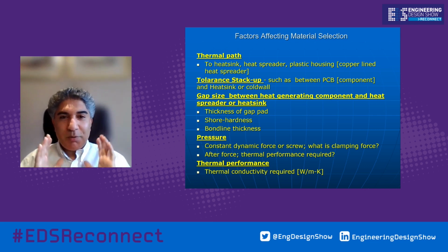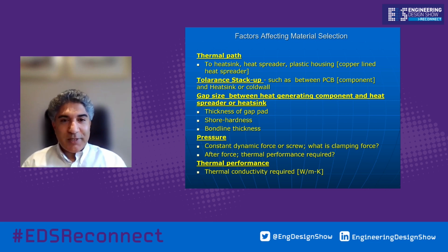Tolerance stack, I probably think that's one of the vital challenges for a mechanical design engineer or thermal stress engineer: the tolerance stack of third-party components and machine interfaces, and trying to have one material handle the various tolerance stack. The gap between the heat sink or the cold wall is another factor, and also how you're going to deflect the material via gap pad so that you don't put more stress on the circuit board and the solder joints. You don't want it to rattle and vibrate if you use a high shore hardness material.